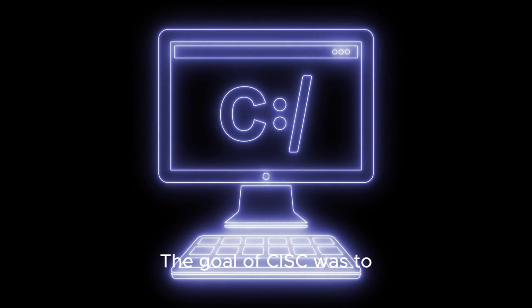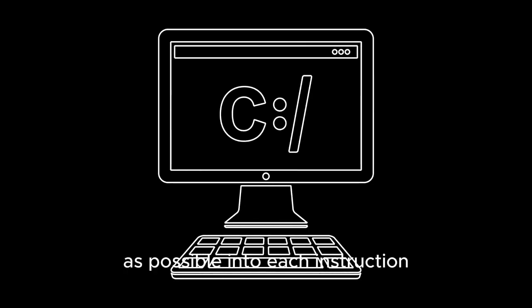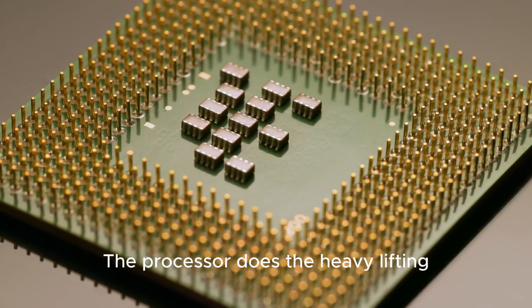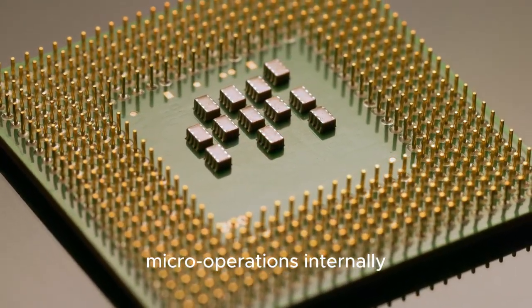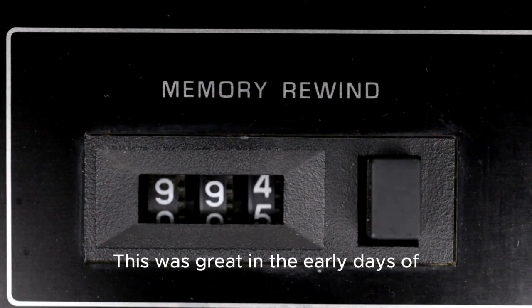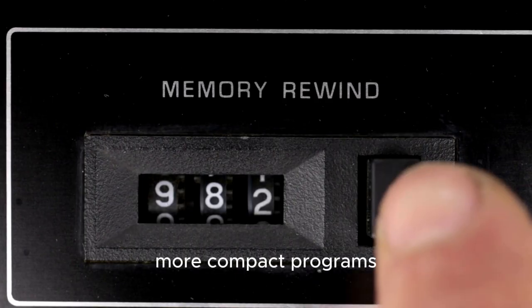The goal of CISC was to make the programmer's job easier by packing as much functionality as possible into each instruction. The processor does the heavy lifting, translating that one command into a series of smaller micro-operations internally. This was great in the early days of computing when memory was slow and expensive. You could write shorter, more compact programs.